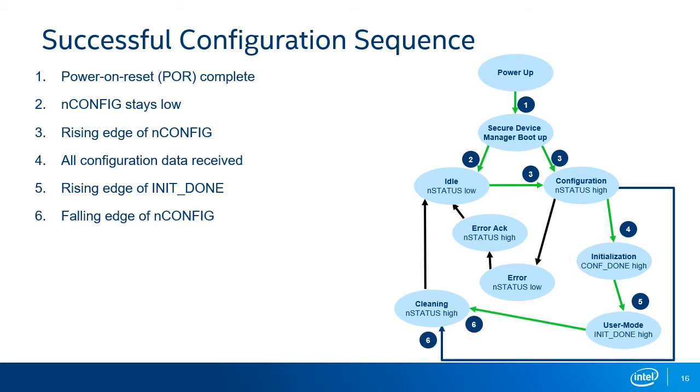A falling edge on the nCONFIG pin causes the device to exit user mode, wiping the user design and going into idle state. The SDM then drives the nSTATUS pin low after the device cleaning is done to indicate the SDM is ready to accept new configuration data.